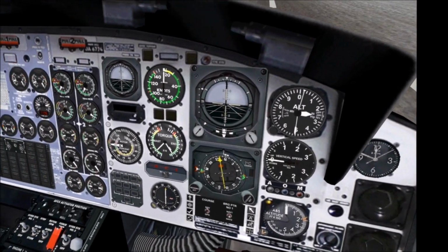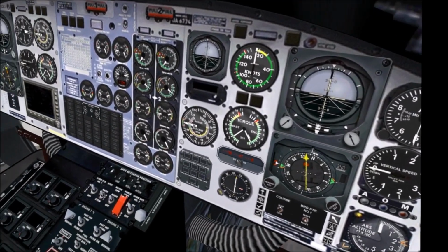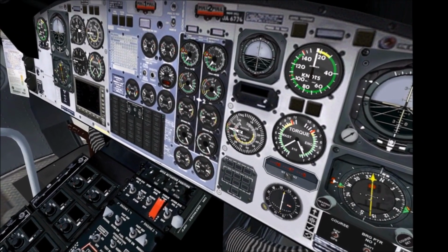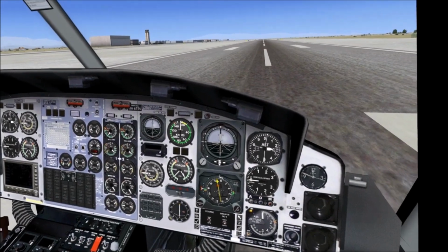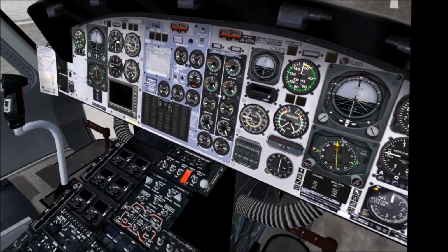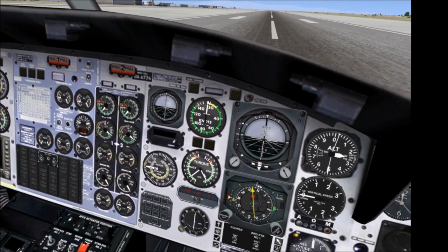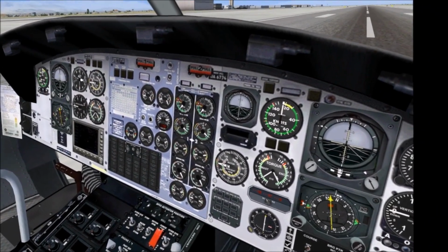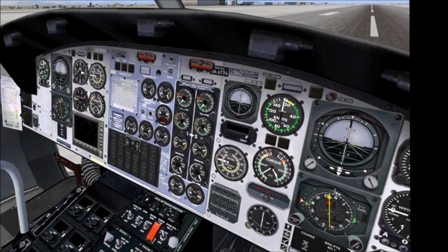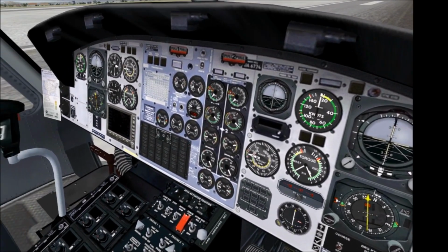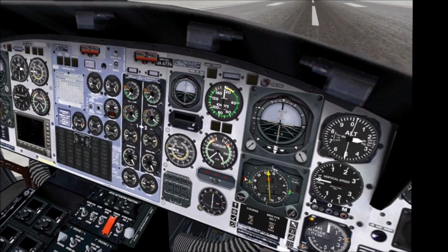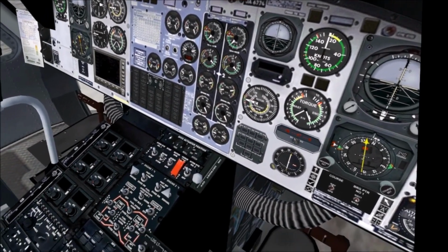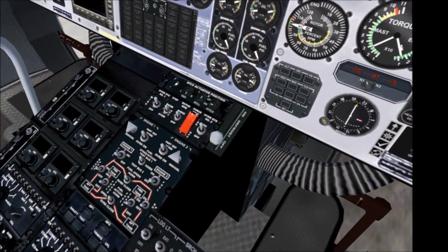Okay, so one thing to note, looking at the panel here, a key difference between this model and the X-Trident model that I need to highlight is the lack of a selection for AP1 and AP2, or HP1 and HP2, depending on which variant of the 412 you're looking at, or what avionics you have installed. So I'm assuming this model was created without the consideration for any sort of artificial stabilization, even though some of those things are shown here.